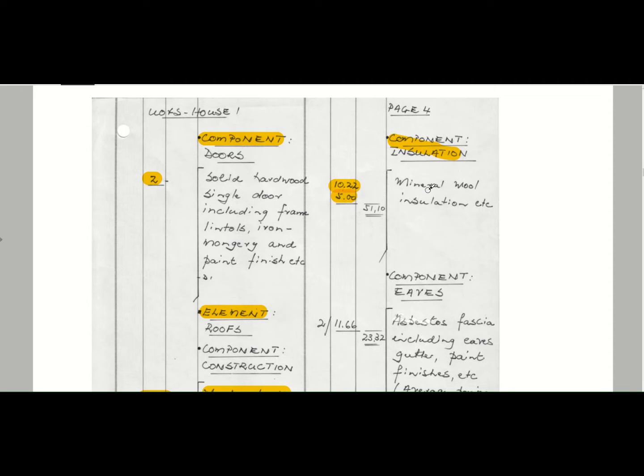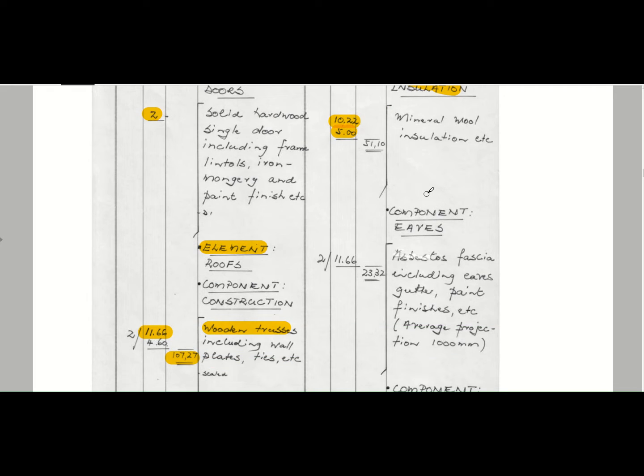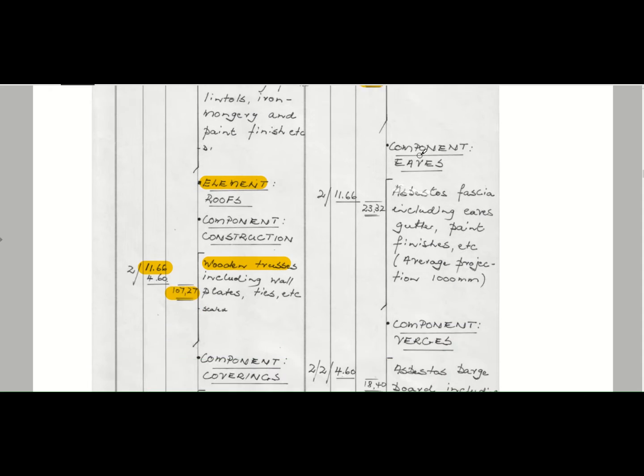So that's your think pink, or many of your houses or examples might have something else, so you don't necessarily have insulation separate. It will be included in your ceiling boards. For instance, if you've got lambda board or iso board or whatever, that will be the item that you use, so you don't necessarily have to measure insulation.